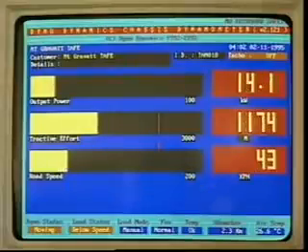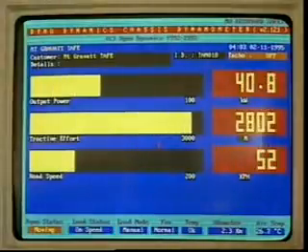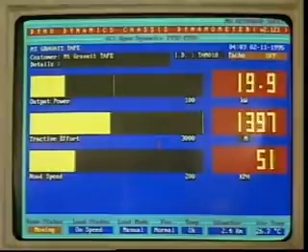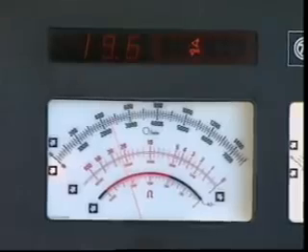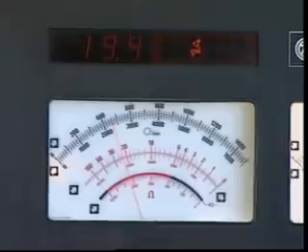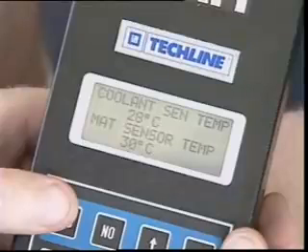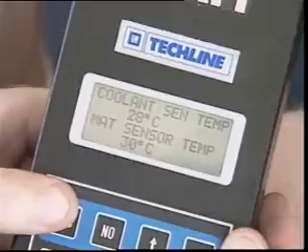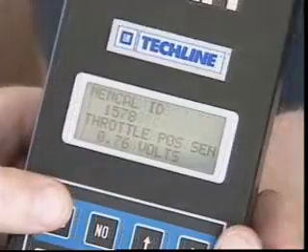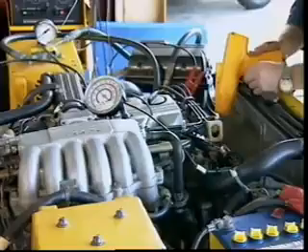Ignition timing is crucial in this process. Between one spark and the next, the ECU uses data it receives on engine load and speed to determine when the next ignition point will occur. It can also correct the map value using extra information such as engine coolant temperature, intake air temperature, or throttle position. Putting all of this together, it arrives at the best ignition point for that operating condition.